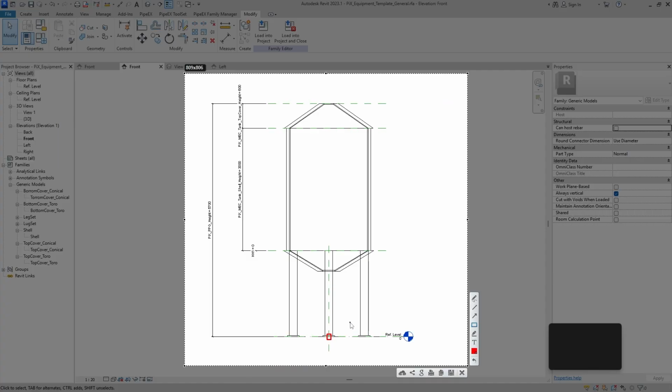So every time when you position it somewhere within the building or on several levels, the base of the family always should be equal to this spot. So reference level always should be equal to the level of placement of the equipment. Then you can have full control over your model. Otherwise it will be chaotic.